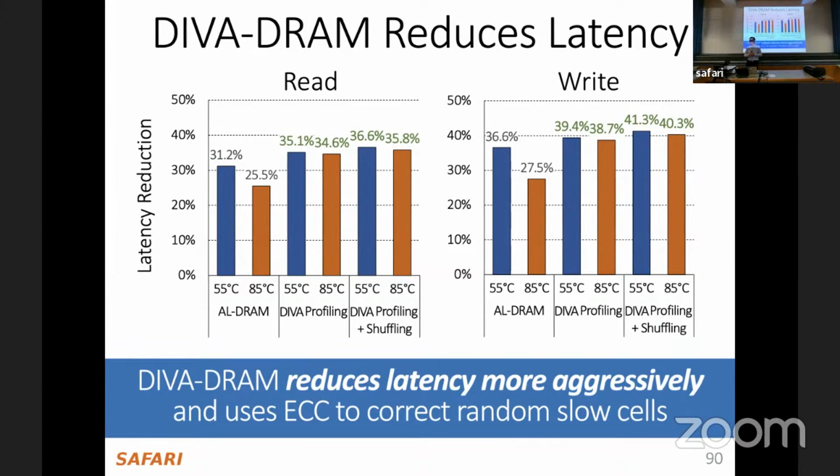How does error correcting code know that's caused by latency? It doesn't know. That's the beauty of error correcting code. You added some redundancy. From the perspective of an error correcting code, you have a bit flip. But because of the redundancy in the way you encoded the data, you can correct for that bit flip.